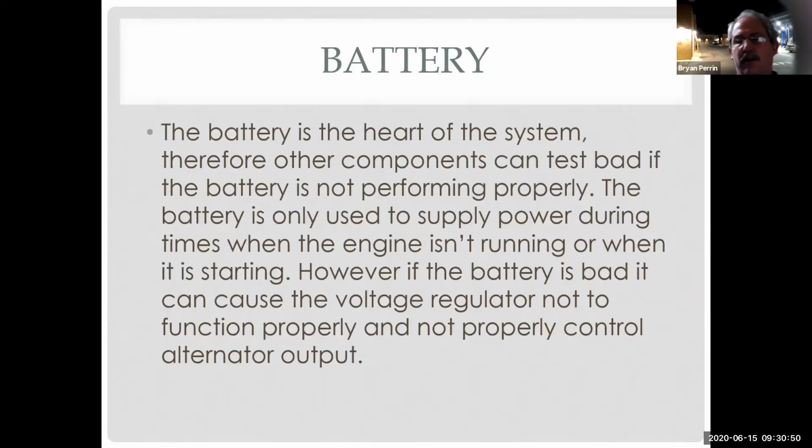So the battery is the heart of the system. Therefore, other components can test bad if the battery is not performing properly. The battery is only used to supply power during times when the engine isn't running or when it's starting. However, if the battery is bad, it can cause the voltage regulator in the charging system not to function properly and not to properly control alternator output. So in other words, if my battery's bad or weak, I can't test my starter because in order to test my starter, I have to have a good supply of voltage.